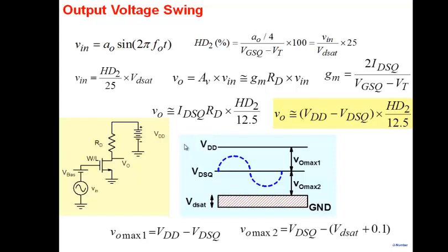There may be some application, for example, if you're driving a motor, where it doesn't matter that it's a perfect sinusoid. Maybe then go ahead and drive it as close as to this. Maybe you don't bother about HD2 at all. Even a square wave is fine for a motor, let's say. Then it's okay. But as I said, in most cases, this limit will get violated before this one here. So what you need to consider then is only these two limits.